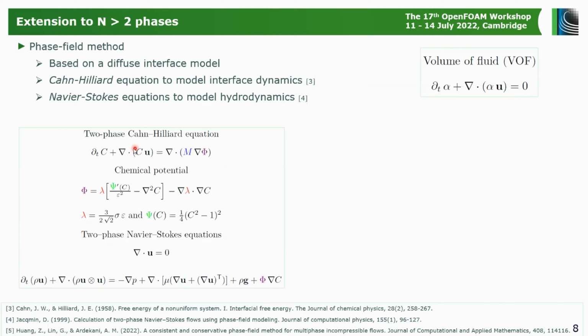And the work that Cahn and Hilliard did was to say that the free energy of a system is not only a function of concentration, but also of the concentration gradient. And this concentration gradient will then contribute to the interfacial-energy-related effects. Now, after computing the Cahn-Hilliard equation, we need to couple it to the Navier-Stokes equation. This is the coupling term, which models capillarity of the diffusive interfaces on the basis of the Korteweg stress tensor.